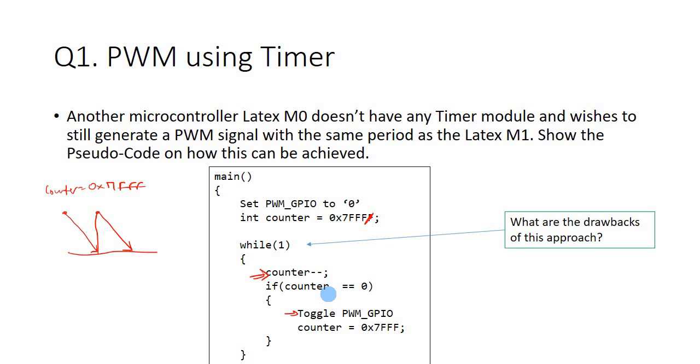And of course, if while this code is running I also have other interrupts in the system, and if those interrupts were to be triggered anywhere while I'm in the while 1 loop, those interrupts will take time. So when I come back, this time difference could always vary, because in between I could have had interrupts from maybe a push button or a serial or something else.